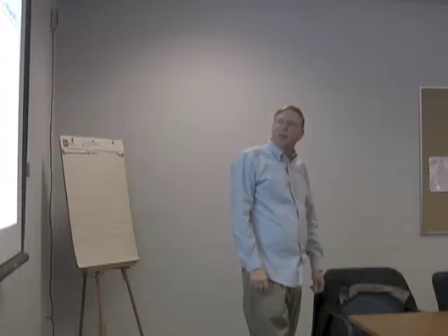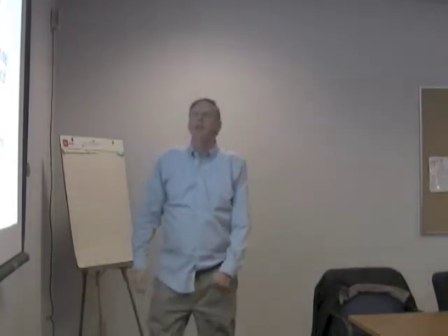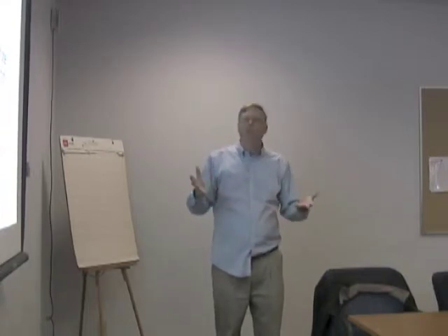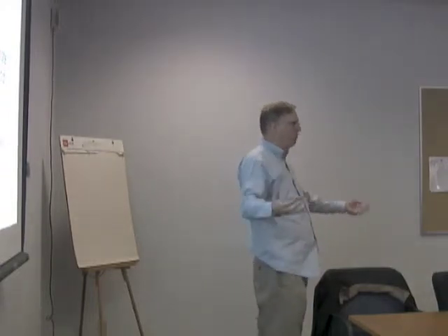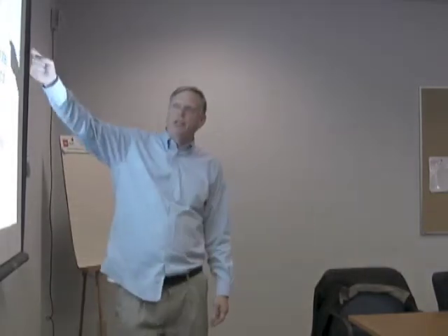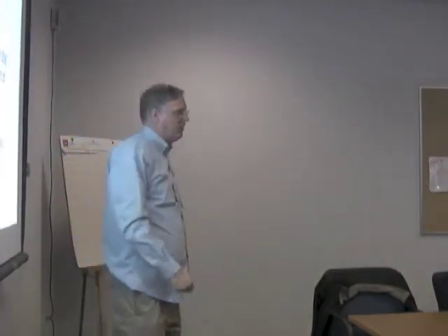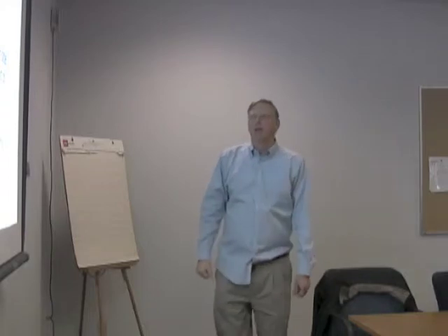The next one. So we've been talking to the seismology and earthquake hazard community about this. So how do you reduce uncertainties in hazard? For the low probabilities used in nuclear power plants, we're on the steep part of the hazard curve. So this conclusion doesn't apply to all hazard calculations. It's really for critical facilities where you're pushing yourself to low probabilities. For steep hazard curves like these, the hazard uncertainty is much more sensitive to the ground motion model than to the source characterization because that slope is about 3. Okay, so there's about 3 times the leverage of a change in the ground motion model compared to a change in the source model.